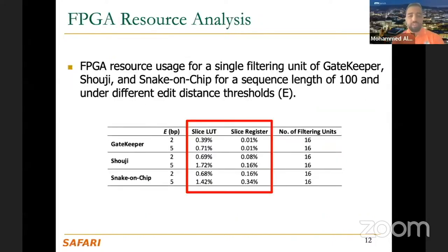So we implement this on GPU, FPGA, and CPU. And these are the results for FPGA resources. So this is the number of lookup tables needed. You can see in most cases it is less than 1 or less than 2% at most. And that is a very cheap algorithm to be implemented in FPGAs. And since it's very lightweight with a very low resource footprint, you can use a large number of replications. So instead of solving a single problem, you can have 50 problems, for example, or 100 problems if the utilization is less than 1%.